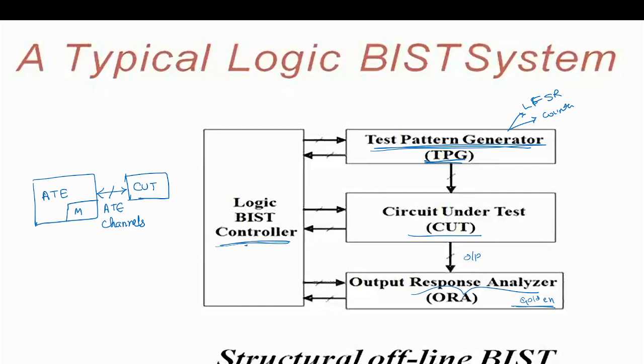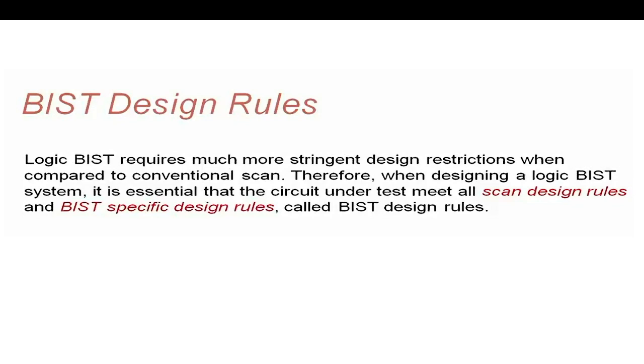Here it is coming to the test mode. Logic BIST requires much more stringent design restrictions when compared to conventional scan. Therefore, when designing a logic BIST system, it is essential that the circuit under test meets scan rules as well as BIST-specific rules.